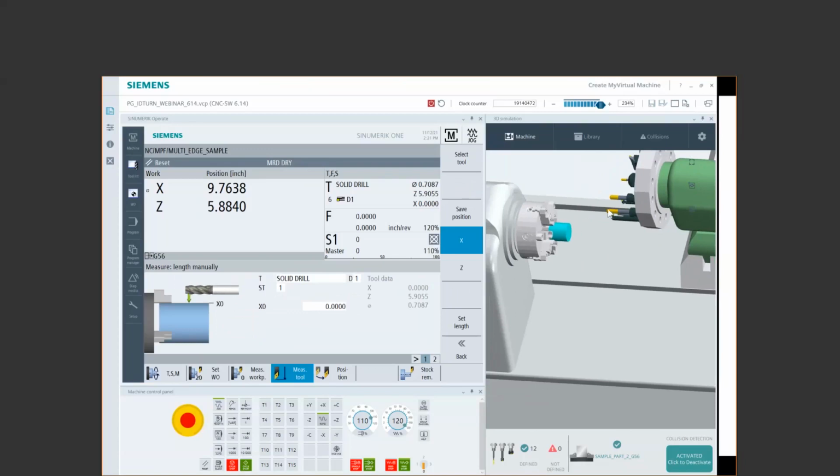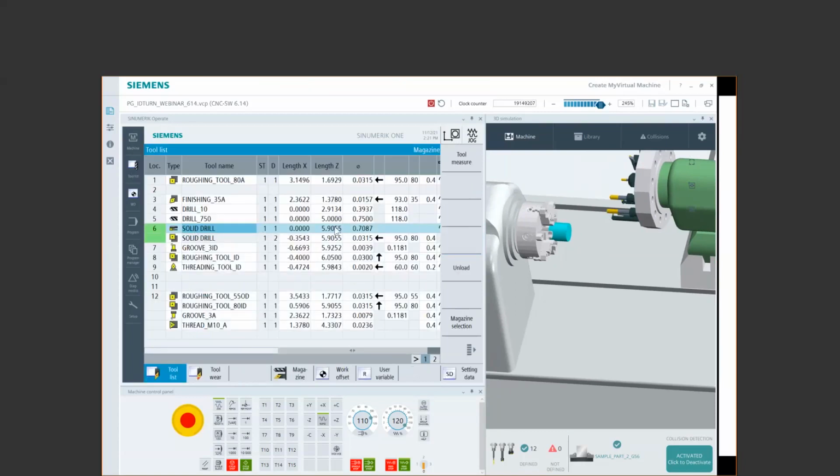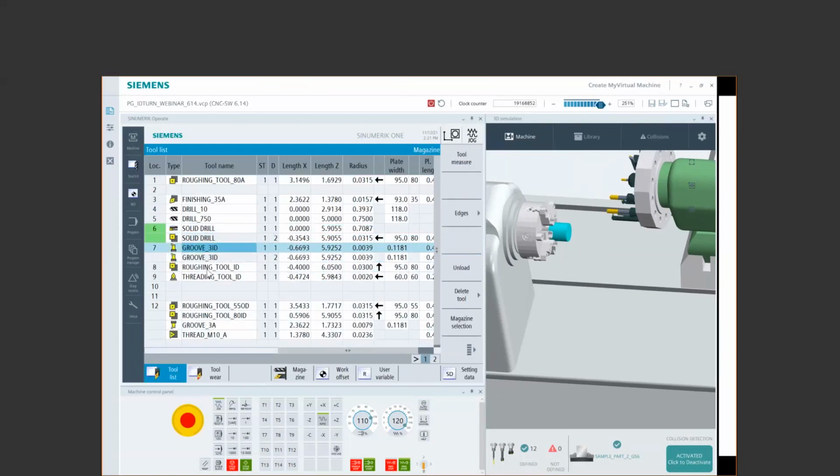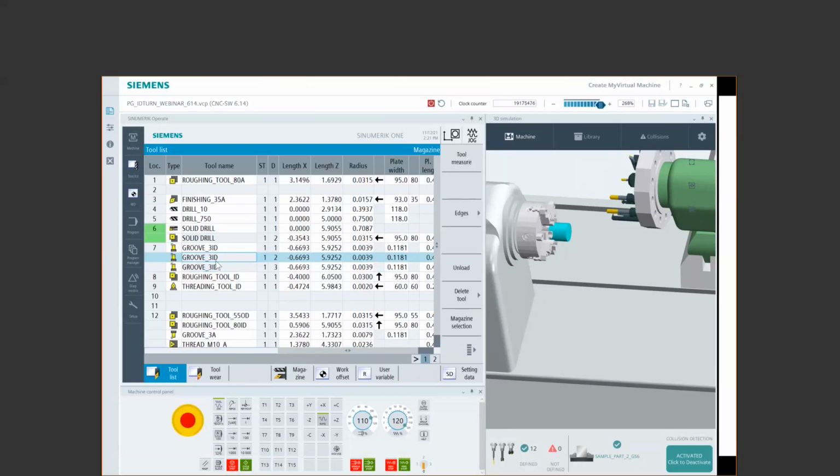But when I want to set up a secondary offset in my offset table, I have my drill already created. So what I did was create a second cutting edge. You don't see the button pop up now because this is the loaded tool. But if I grab any different tool, you see where I get this little cutting edge button. Once I say yes, I want another cutting edge, see how it created a new line here? And I can keep doing this up to 9 times.